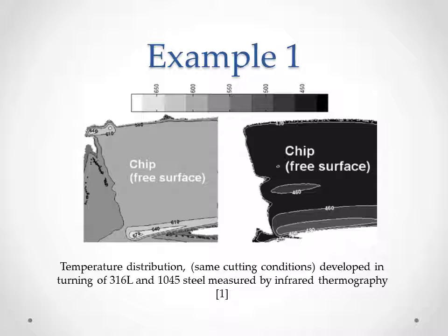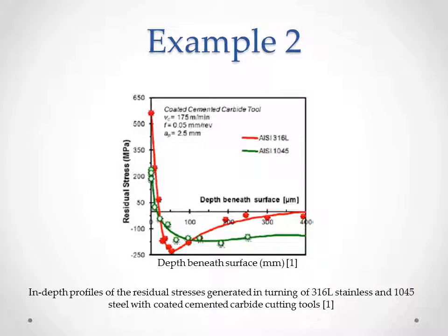The cutting parameters were identical, same speed and feed rate, the same tool, the same machine, and you can see the increased energy that was inserted essentially to cut the stainless versus the regular steel. So that ties it back to our previous discussion of how it takes a lot of energy to cut and deform these materials, and consequently a lot of heating takes place.